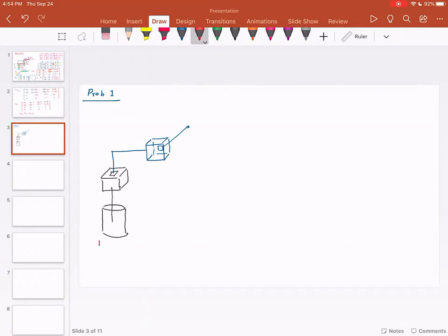This is my first revolute joint. Then this is the second prismatic joint, and this is the third prismatic joint. So this is an RPP robot. According to our technique, I'm going to assign Z0, Z1, and Z2. And I'm going to add one last, Z3. This is my end effector. To my end effector, I will add Z3.